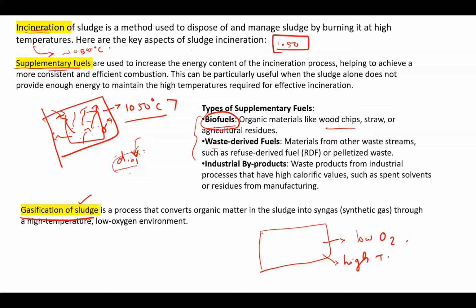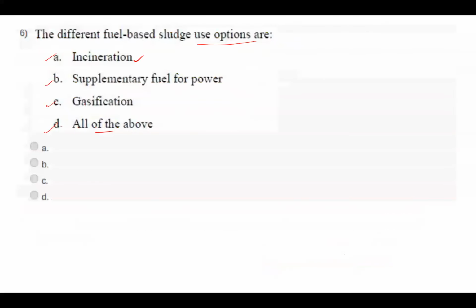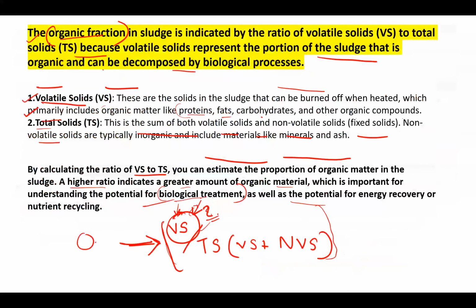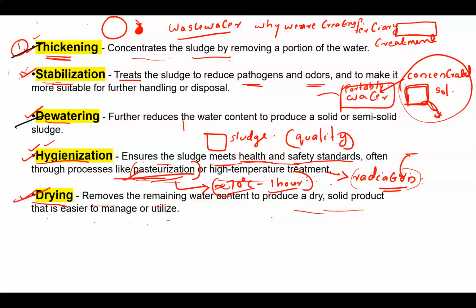Yeah, both are different. As I explained, in the sludge thickening process we have to thicken the sludge. Dewatering is there in between the steps when we handle the sludge. But we also need to stabilize the whole sludge. So after the stabilization, if some water content is there, we can de-water it from the system.